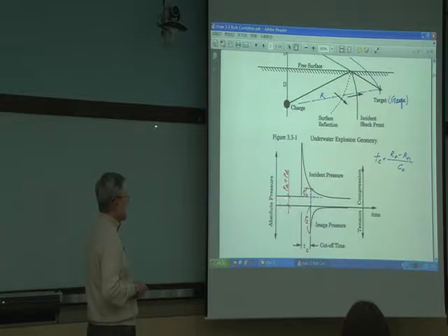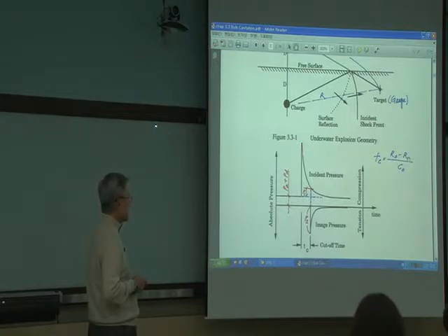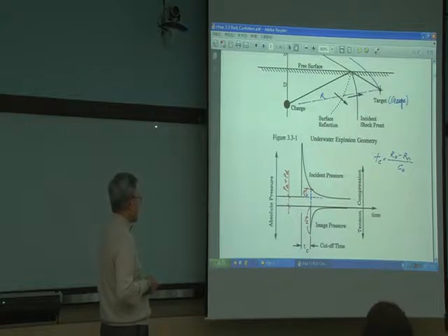And to compute the bulk cavitation zone, you have to pick out a point near the free surface. Then you have to compute the pressure. Then make sure the pressure has to be 0 or less than or equal to 0. And this is hydrodynamic pressure plus hydrostatic pressure, from the free surface up to the point that you have interest to compute. So PA is atmospheric pressure.